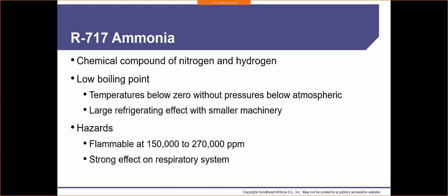So it's great. The problem is it's extremely flammable, and it has strong effects on our respiratory system. So you really have to be specialized to even work on ammonia equipment. They're just not going to let anybody do that. I think there's only one outfit in the Chicagoland area, maybe two, that do work on ammonia systems. If there is an ammonia leak, it's like one of those things that you see in the movies. The entire hazmat team's there evacuating people, because it is a very dangerous refrigerant. So keep that in mind, but it does do well as far as handling sub-zero temperatures.